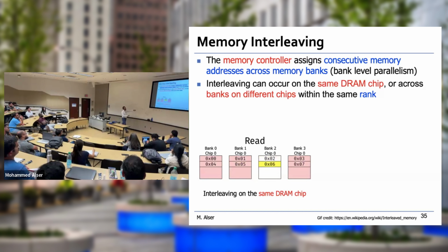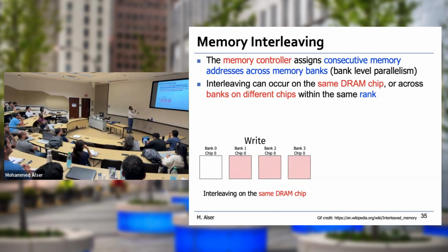So imagine you have a data block. The data starts from here, which is 8 of those rows, 8 rows in the bank, whatever the size of the row. So you could divide them equally, and we call this division 4-way. We call it 4-way because in the first way, we start in bank 0, then 1, 2, 3, and then iterate.